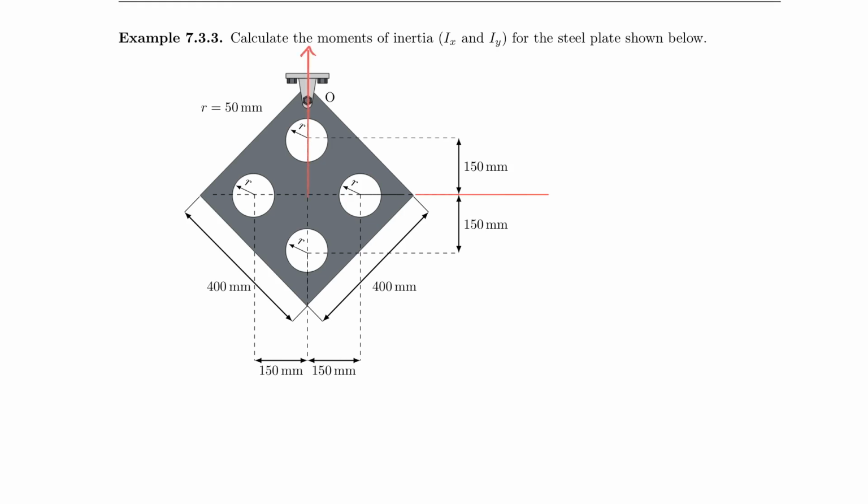close to the centroid. And so what that means, so let's say I take the moment of inertia about the x-axis here that I just drew for you, then you will find that these 2 blue circles have a centroid location here and here, and they are removed from the total centroid location, which is right there. However, if I look at these purple circles, they actually have a centroid right there and right there, and so they are not removed from the centroid of the total shape.